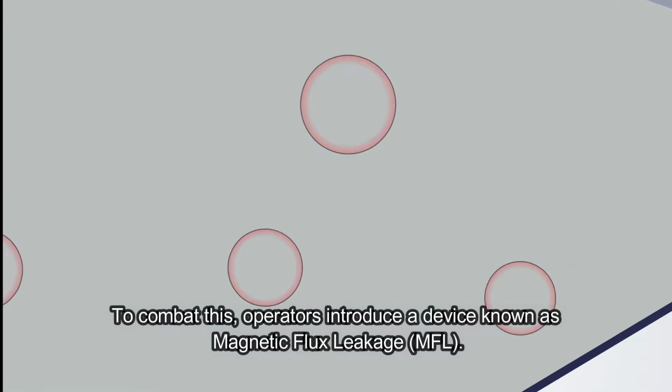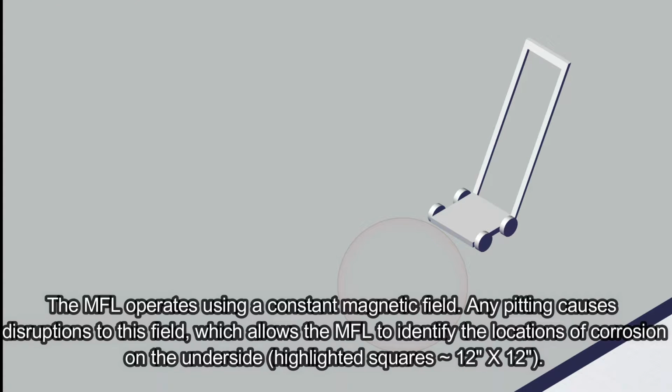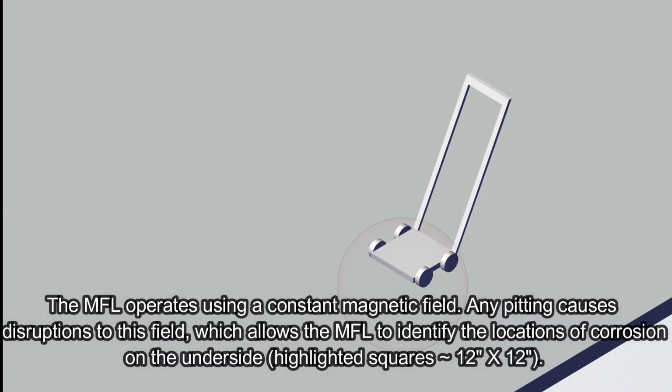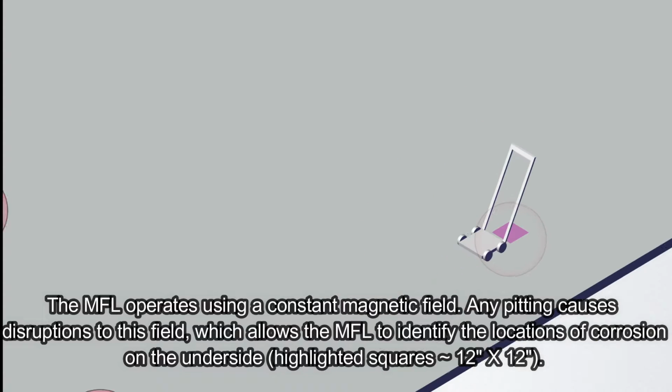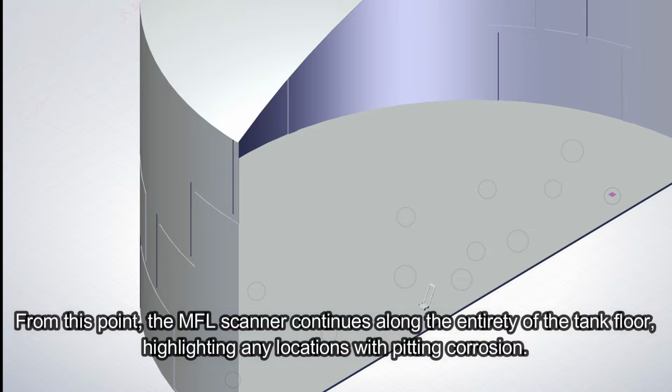To combat this, operators introduce a device known as magnetic flux leakage, or MFL. The MFL operates using a constant magnetic field. Any pitting causes disruptions to this field, which allows the MFL to identify the locations of corrosion on the underside. From this point, the MFL scanner continues along the entirety of the tank floor, highlighting any locations with pitting corrosion.